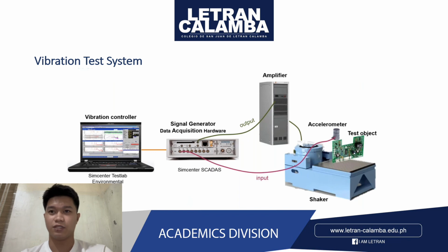Then we have data acquisition hardware, and this is used for both acquisition and output. Next is the amplifier. What the amplifier does is it will gain the signal from the front end and input that into the shaker. Then we have the shaker, which is typically either an electrodynamic shaker or a hydraulic device that has a moving mass to recreate the vibration levels. There are horizontal and vertical shaker tables depending on your test type.